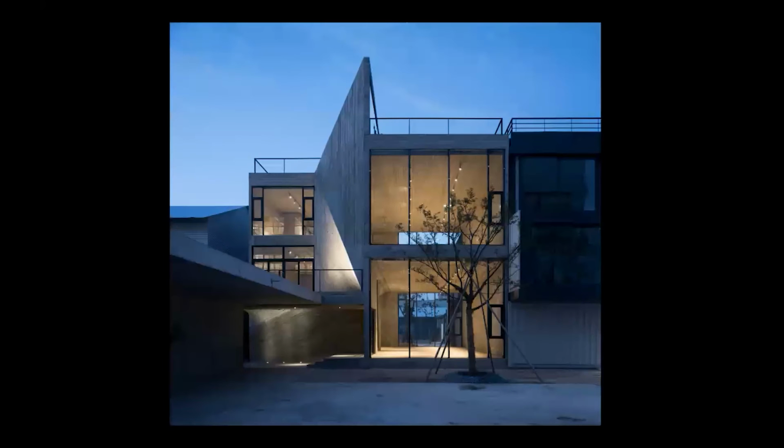The second project was designed in 2015, Fab-Union space, which is also located on the westbound of Shanghai, made of concrete. We changed to another material. The span of this building is 14, 15 meters. We try to create 2 very high spaces, 5 meters and 3.3 meters, so it's totally 10 meters, 3 floors, 2 floors. We don't want to put a column in the middle, but as you know, it is impossible to create a concrete structure with a 14, 15 meter span that way. So we try to introduce a stair in the middle, which is not only circulation space, but also structure space.